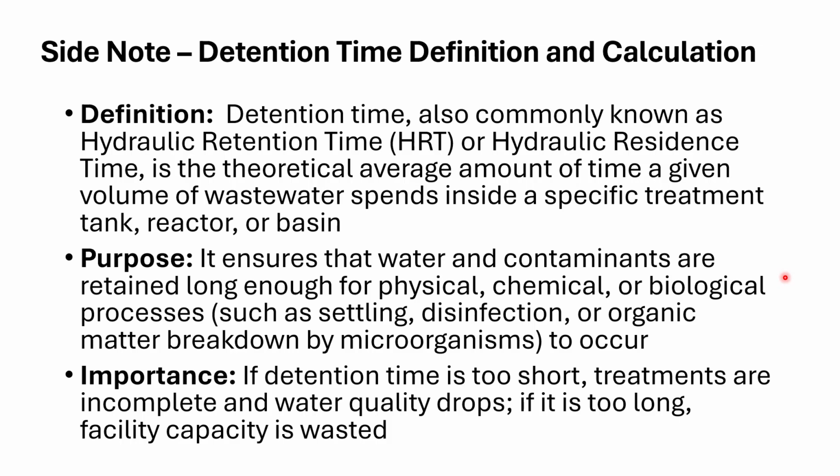Okay, so we make sure that the wastewater is in the process, whether it's a physical, chemical, or biological process like settling, disinfection, or metabolization of the organic matter by microbes. So the wastewater is going to hang out long enough for whatever process we're subjecting it to occur.